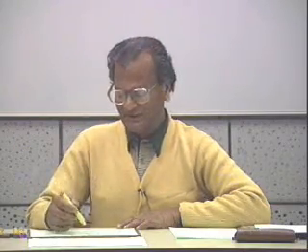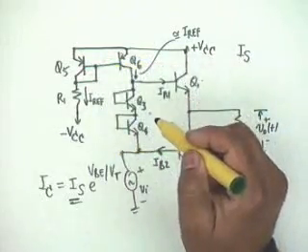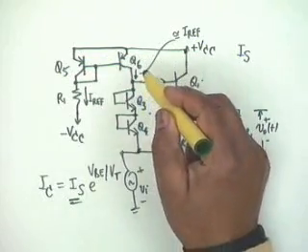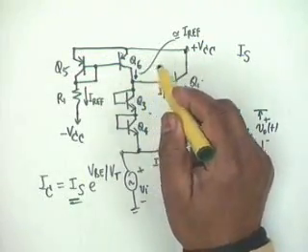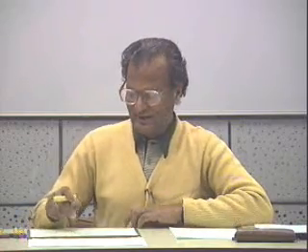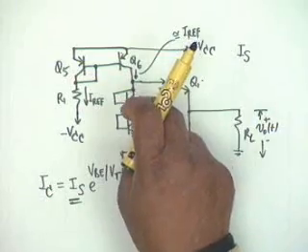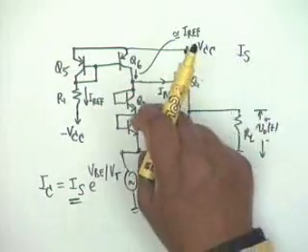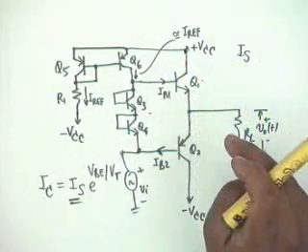And therefore, there are 4 transistors here. If you can reduce the junction area to 1/4, then this would be equivalent to fabricating 1 silicon transistor of a larger capacity. Agreed? So IS3 and IS4 would be much smaller compared to Q1 and Q2, in a ratio of 1:4. This is what people use in fabrication.